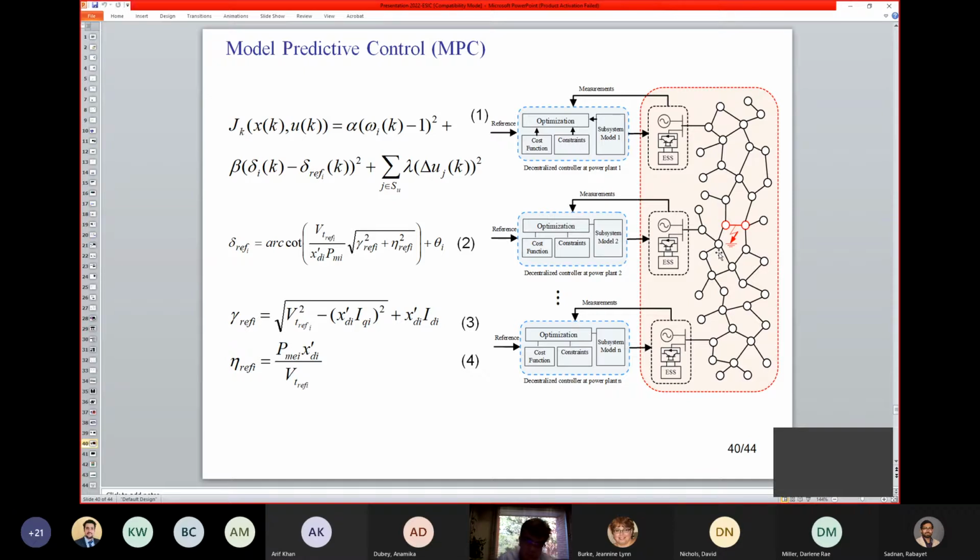One very important problem that is sometimes overlooked is that during that process, you should make sure that the voltage level at the terminal of the generator is not more than a certain level. Because while you are working on transient stability, your overvoltage protection devices may operate, because you go out of range.